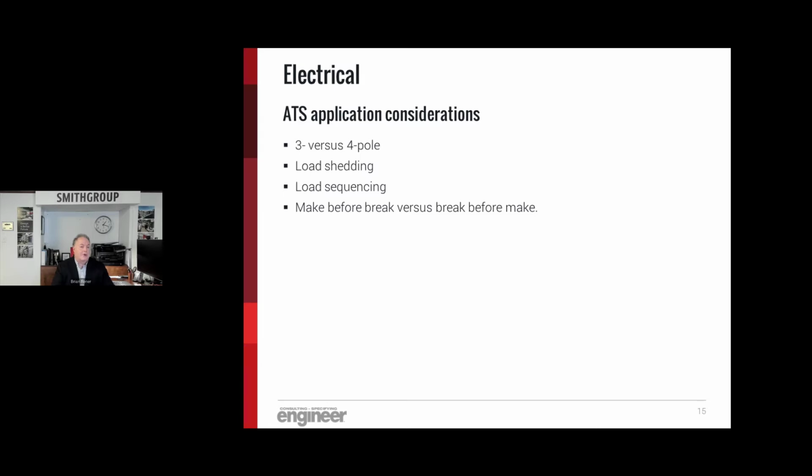On a break before make, there's actually an interruption, a small interruption of the power to move over. Just make sure you coordinate with the utility, because they don't like your on-site power sources paralleling, even for a millisecond, with your on-site power.